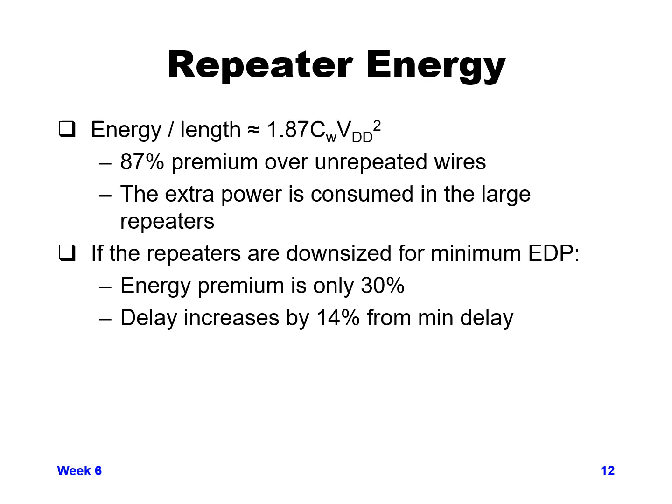So if you add really large repeaters in order to minimize your delay, it could add extra power to your design. And so sometimes you might want to balance your power versus your delay and put in smaller repeaters than would guarantee you the minimum delay, in order to reduce the additional power that gets added to the design.